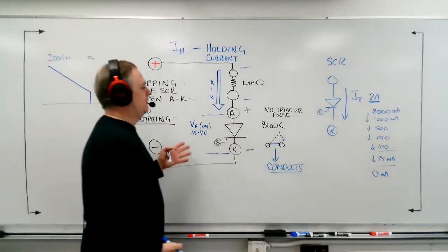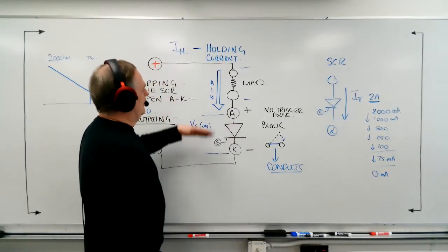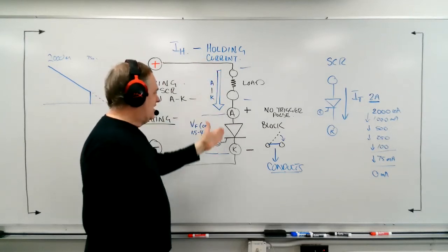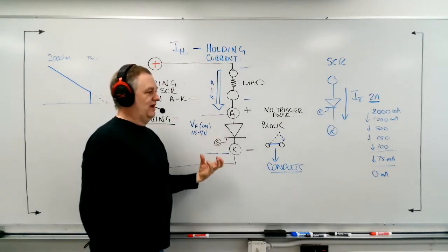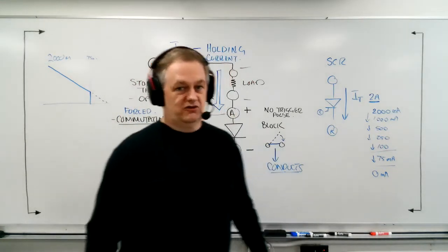So holding current is going to be a very important feature of this for us, and just understanding that it's actually the A to K current. When it gets down to this value, it will no longer actually hold in the circuit.